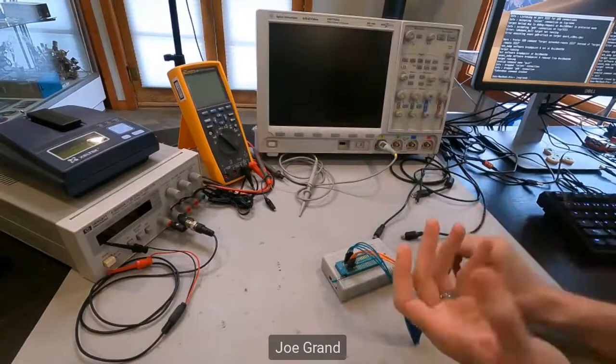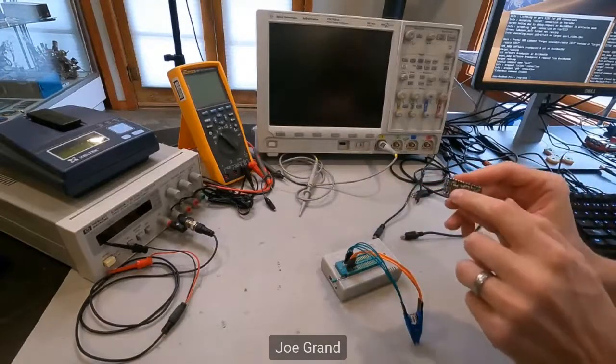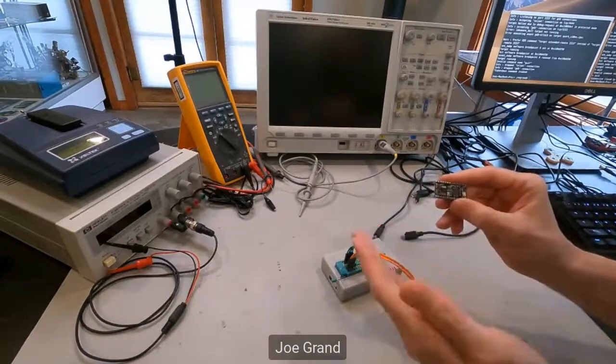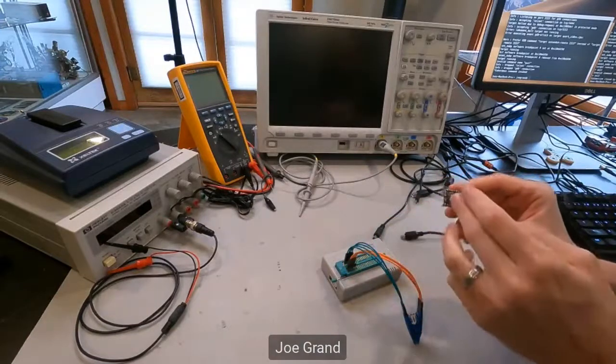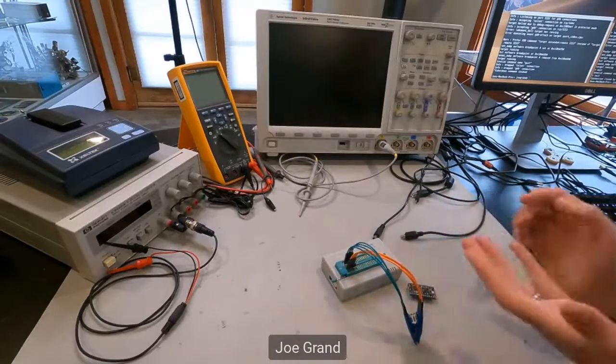There are certain parts that are ball grid array, BGA, which basically, instead of having visible pins on the chip, everything is connected underneath the part. That's going to make it really hard to deal with. So if we can read chips in circuit, that's a lot better.